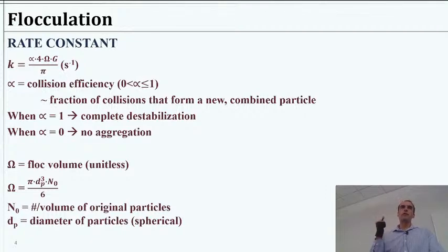The collision efficiency is basically the destabilization. When we talked about coagulation to allow the particles to stick together, this is how well did that work? How likely are they going to form a new particle when two particles meet? If they're completely stable, then they are doing the stiff arm thing and never touching each other, right? If they're stable, that means they're going to float around there and not settle. So completely stabilized particles would have a collision efficiency of 0, which doesn't quite make sense.